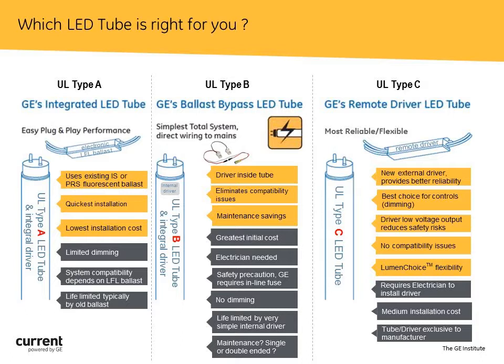Finally, if you're concerned about the reliability of your new LED system, understand that you're putting on a very long-lived lamp. That lamp is going to be used on potentially a very old fluorescent electronic ballast. The life of the product is going to be rated on the weak link in the chain, and therefore the old ballast is going to set when that system's going to fail. So those are the pros and cons for Type A. It's about 3 and 3.